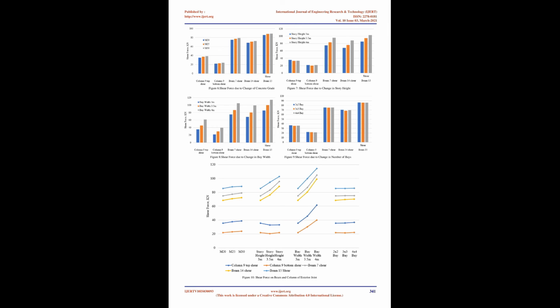According to NZS 3101.1:2006, V*jh is calculated by clause 15.3.4 as 0.75, not based on overstrength. Aj and Ajv are calculated using the NZS code. The NZS code provides vertical and horizontal shear stirrups over a length of the effective depth of the column and beam. As the grade of concrete increases, joint shear reinforcement also increases.